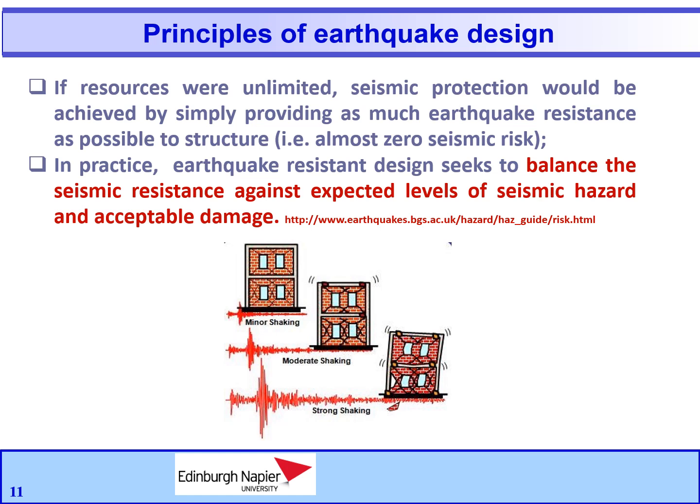In practice, earthquake-resistant design seeks to balance the seismic resistance against expected levels of seismic hazard and acceptable damage. Obviously, some facilities demand greater earthquake resistance than others because of their greater social and financial significance. It is important to determine in the design brief not only the more obvious intrinsic value of the structure, its contents and function, or any special parts of it, but also the survival value placed upon it by the owner.